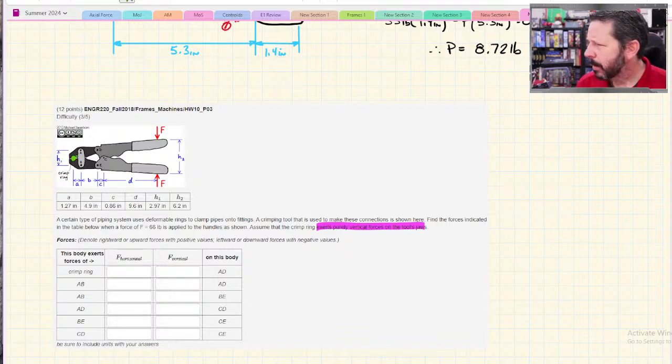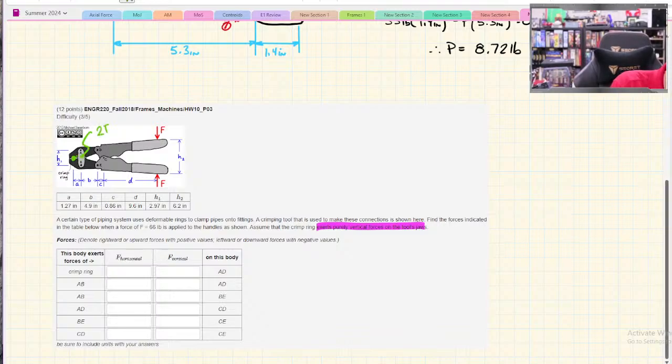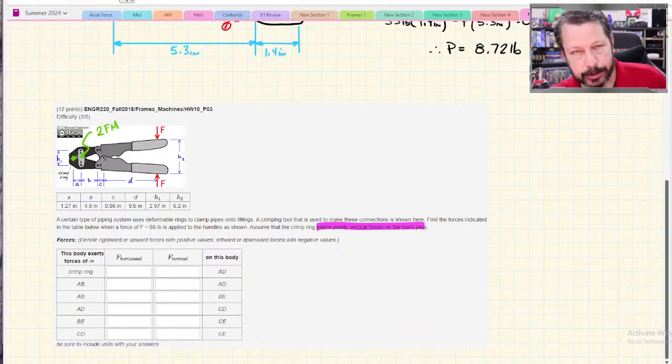And the other thing with this is part AB is a 2-force member. So part AB is just a vertical piece. Doesn't matter what orientation it is, but it is vertical in our picture. It has 2 pins, A and B. There are no forces acting on part AB other than at the pin at A or B. So AB is a 2-force member. So that could come in handy. So we really only have 2 pieces to work with plus this 2-force member.